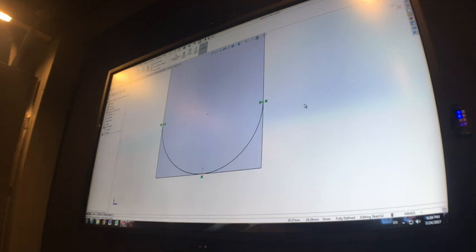Okay. Now the other thing that this has given us is a center point with which we can put our circle. So I'm going to grab the circle tool. For anyone that wasn't here last week, the main way that we're going to select our tools for lines, rectangles and circles is with mouse gestures. So how to do that is you right click on your mouse and you drag, and you can drag left for a line, down for a rectangle, or right for a circle. You can also drag up for the dimension tool.